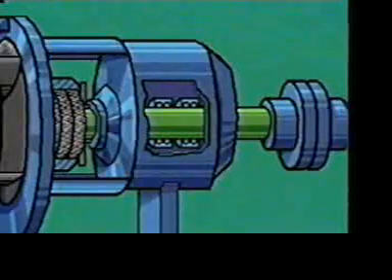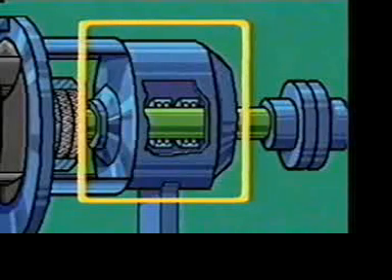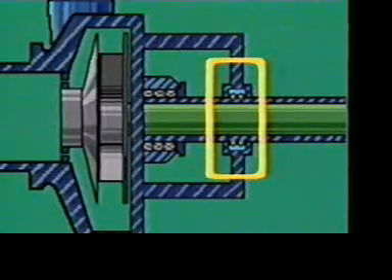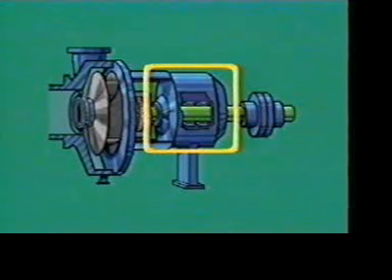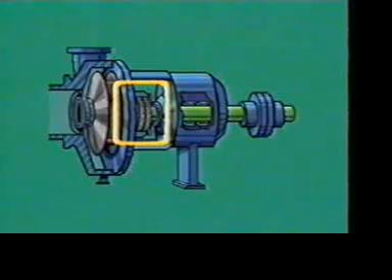Now to bearings. They support the shaft and reduce friction as it rotates in the casing. They do even more. They control the forward and backward movement, the thrust of the shaft, as well as the shaft side-to-side or radial movement. That keeps the shaft from rubbing against the pump casing. Bearings can be here, in the pump casing on small process pumps, or separated in special housings on larger ones. Last are seals, or packing. They're used to stop or cut fluid leakage around the shaft.